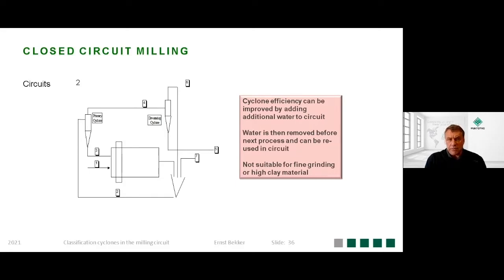But that's one option of reducing the feed density to a primary cyclone, thereby reducing the amount of misplaced fines to the underflow. Because the bypass water formula was the water in the underflow divided by the water in the feed. We can make the spigot as small as possible before it goes into roping, but then we need to add water in the feed. And if there's not a lot of water in the feed to the cyclone, your cyclone is still not operating efficiently.